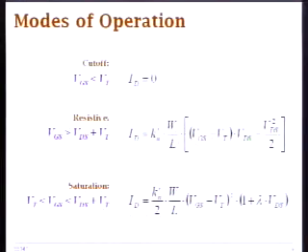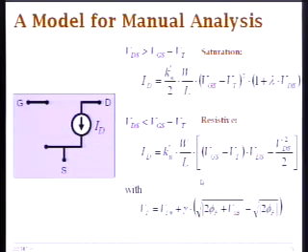Okay, going back to slides. So this is a summary of all these equations for the long channel. And then you can model a transistor using this model. You can look at your transistor as an equivalent current source that has different expressions for current depending on the regions of operation. And we identify saturation and resistive modes as the most important, with this threshold parameter given with this formula here.